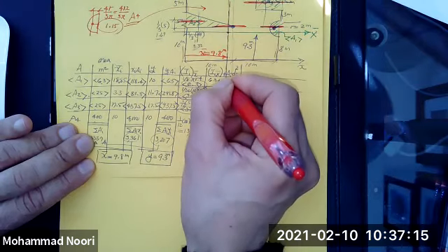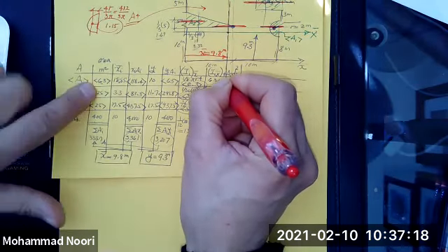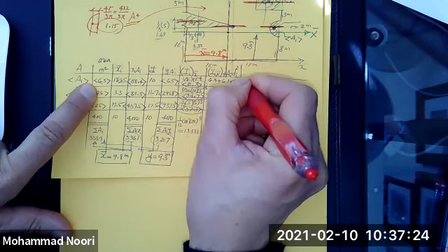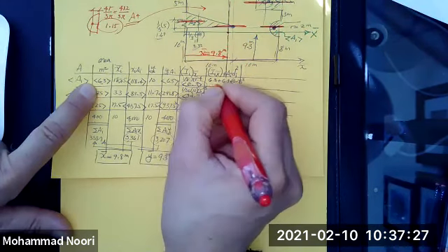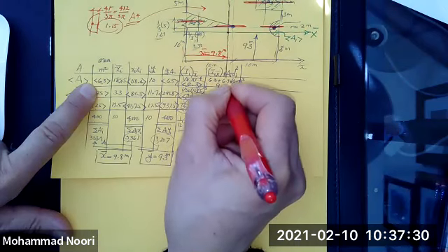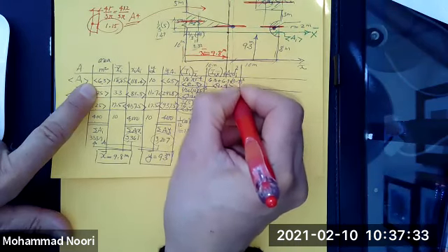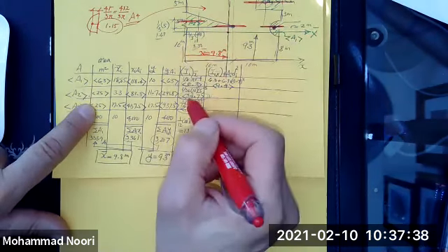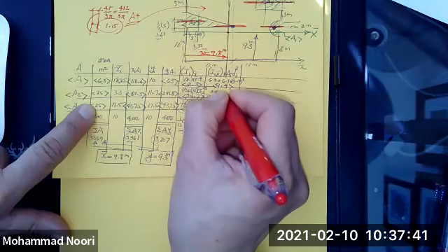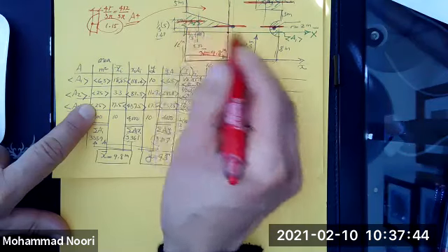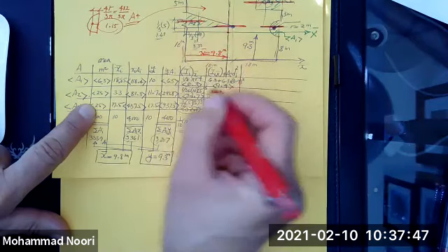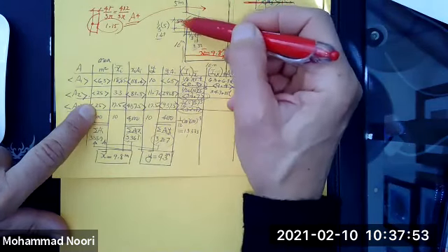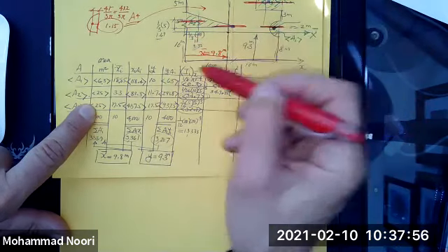So I just add the area of that, which I have here: 6.3 times 0.7 squared, and write it here. That would be 9.4. Same thing here. Just write this value, 34.7, add to it the area of this shape, which is 5 times 10 divided by 2, you have it here, 25, times the distance from here to here squared.